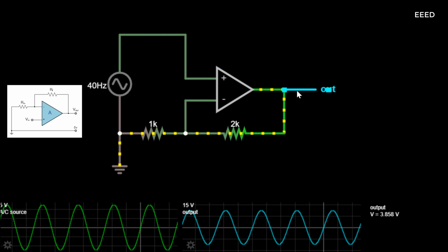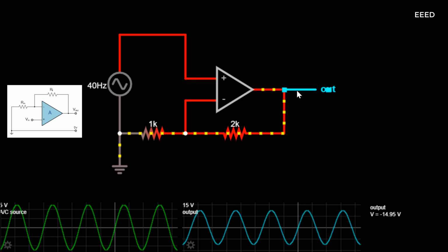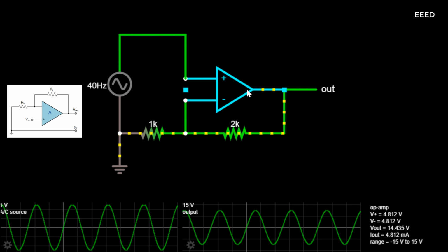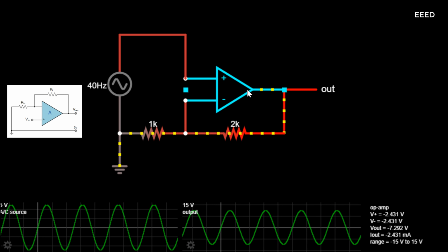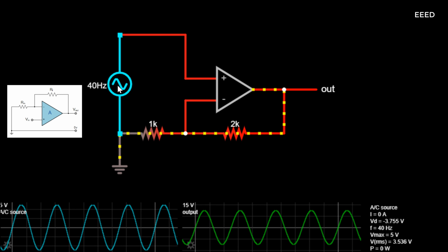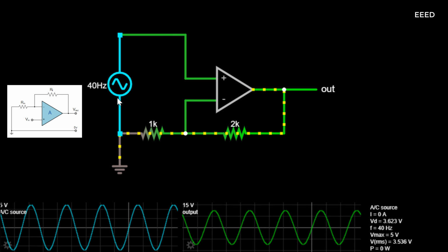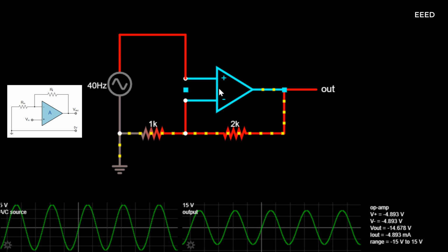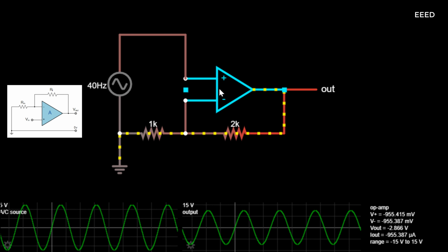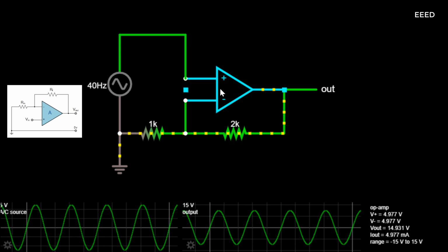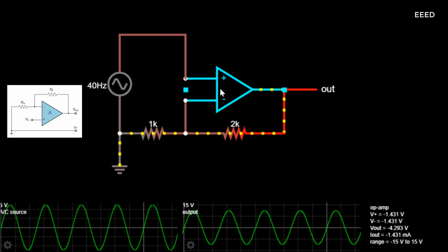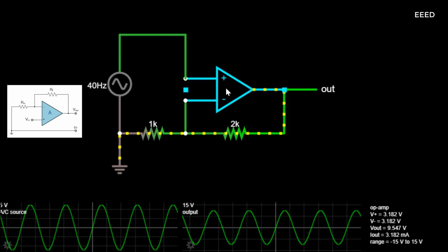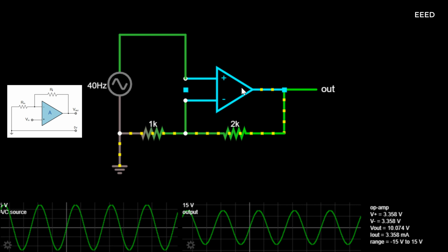Voltage follower, unity gain buffer. If we made the feedback resistor RF equal to 0, RF = 0, and resistor R2 equal to infinity, R2 = infinity, then the circuit would have a fixed gain of 1, as all the output voltage would be present on the inverting input terminal, negative feedback. This would then produce a special type of non-inverting amplifier circuit called a voltage follower, also called a unity gain buffer. As the input signal is connected directly to the non-inverting input of the amplifier, the output signal is not inverted, resulting in the output voltage being equal to the input voltage, Vout = VIN.